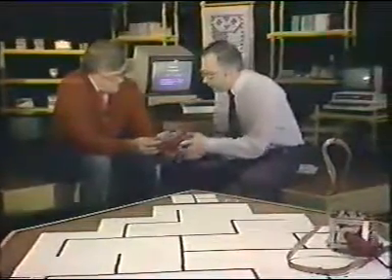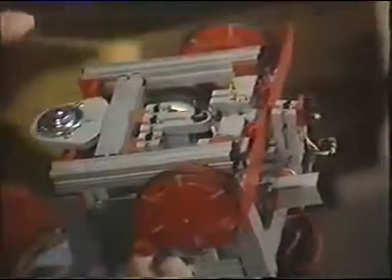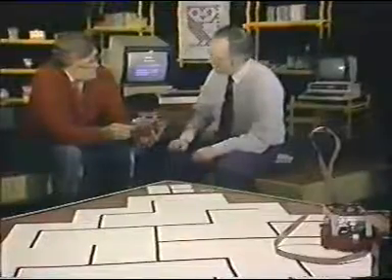Well, those are the input devices, and we've also got some output devices here. Right, well, we've got two output devices. There's a stepper motor here and a stepper motor over here, and as well as that, there's a device for moving the pen up and down. The stepper motor just moves it around one click at a time at about 7.5 degrees. When you give it one digital pulse, it moves, as you say, a very small angle.